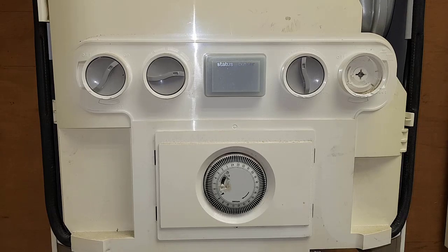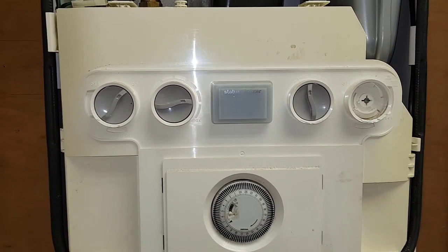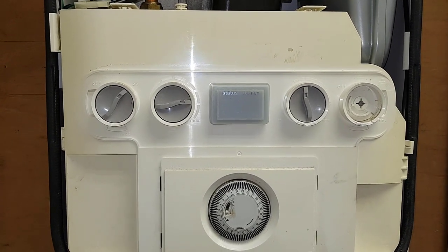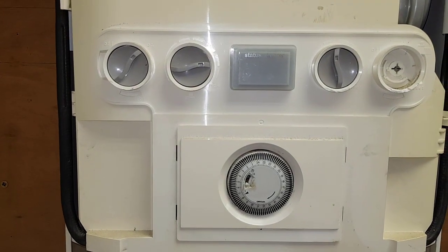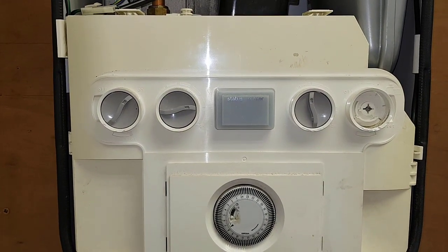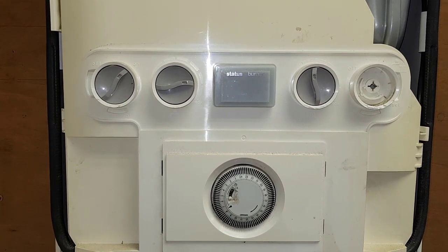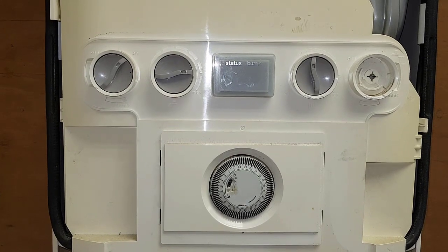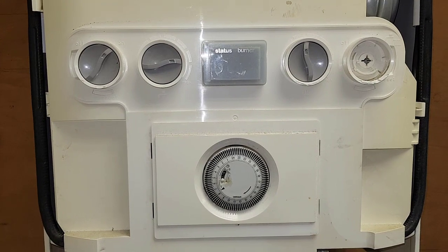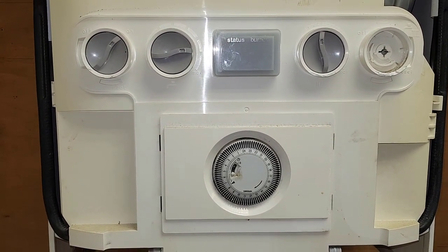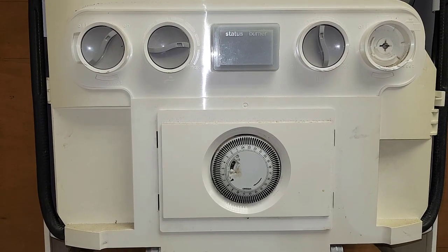Okay, so now we're going to look at the next item on your quadrant for no central heating: closed isolation valves. On this particular boiler, the way it's designed, people might be losing pressure and topping it up quite frequently, and can accidentally turn off the flow or return isolation valves. They might not realise they've done that.